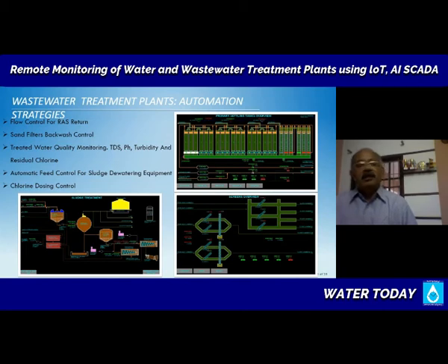backwashing them is a big task. So you do them sequentially so that you can operate the plant with a minimum number of scouring air blowers, and optimally drain the system, because if too many sand filters are backwashing simultaneously, then the drains will be overloaded. So everything can be automated by sequentially backwashing the sand filters.